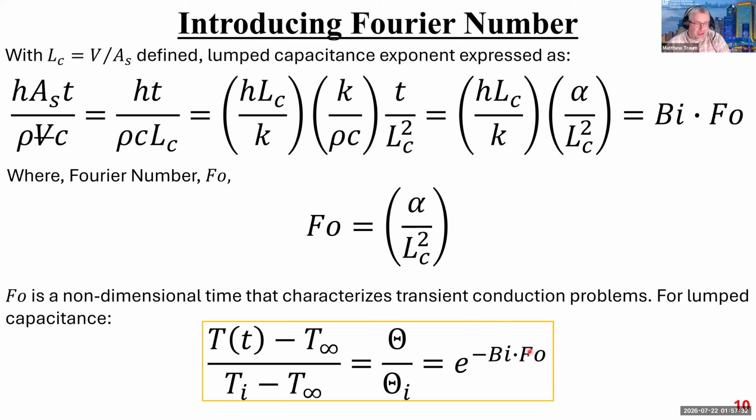Now, if you took fluids with me, you hopefully remember that I am a big fan of Buckingham Pi dimensional analysis, and this equation is completely dimensionless, right? There are no dimensions here. This is a ratio of temperatures, so units cancel out. Biot number is unitless, Fourier number is unitless. They're multiplied together, so two unitless things multiplied together is another unitless thing. So think back to fluids, this is the functional relationship between the Biot number, Fourier number, and the temperature ratio,